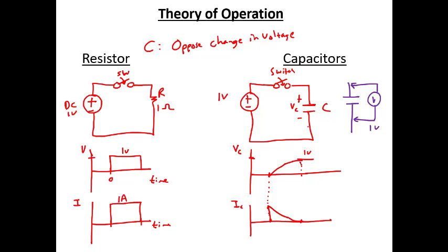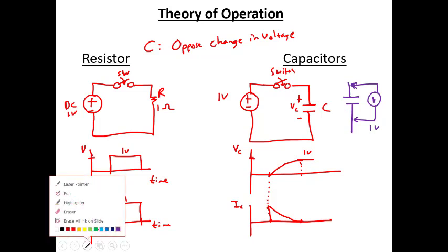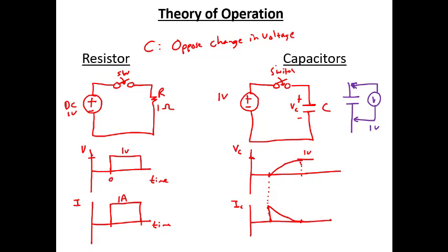So the capacitor is going to store energy, and if you touch a capacitor, this is one of those safety things, you want to be careful because this will store energy for a very long time. If you had one of those big TVs that were built back in the 80s and 90s before there were LCD screens, they had capacitors in there, and you'd always see warnings if you took the plastic covers off that the capacitors will not discharge just because you removed the power. The only way to discharge a capacitor is to make a connection between the positive lead and the negative lead.